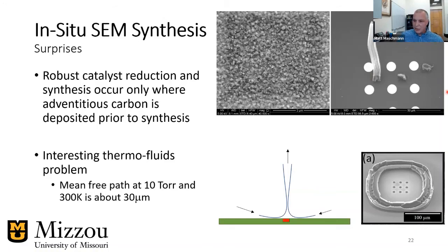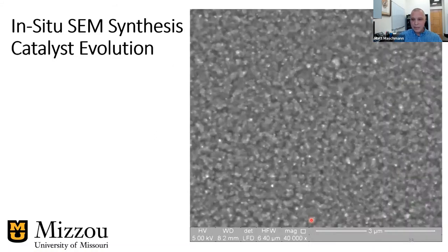If you look at this figure labeled as A at the bottom, we get this kind of stadium growth around the heated zone. If we nuke our chip and send it to like 1200 degrees C, the region outside of our uniform heated zone heats up to an appropriate growth condition of like 600 or 700 degrees C. And we see that outside of this central heated zone, we're starting to get this concentric growth. And we would expect in that region that we wouldn't necessarily have a stagnation point. So we're working to understand that better. And that all by itself is kind of an interesting problem.